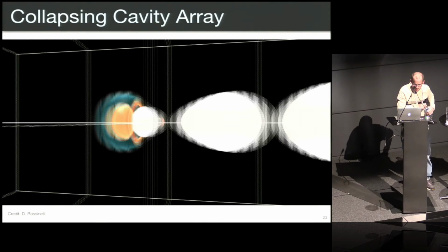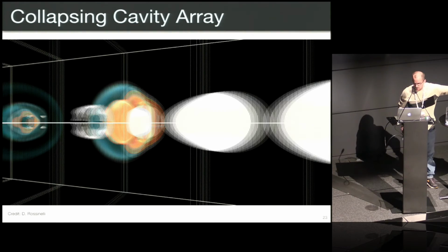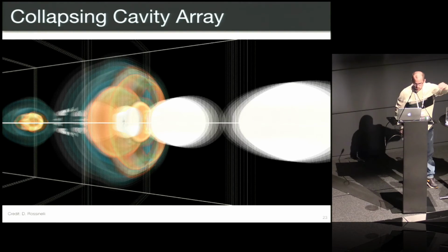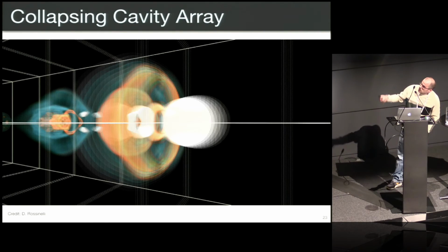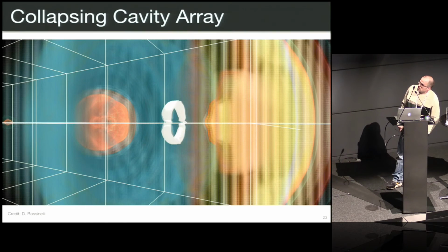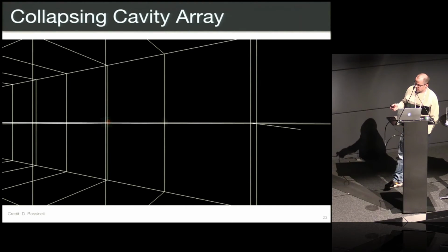We can see a highly non-spherical collapse of the bubbles and also some pressure rebounds in the upstream field due to already collapsed bubbles. There is a velocity jet penetrating through the bubbles, which causes this non-spherical collapse, and we observe a maximum pressure peak for the very last bubble.